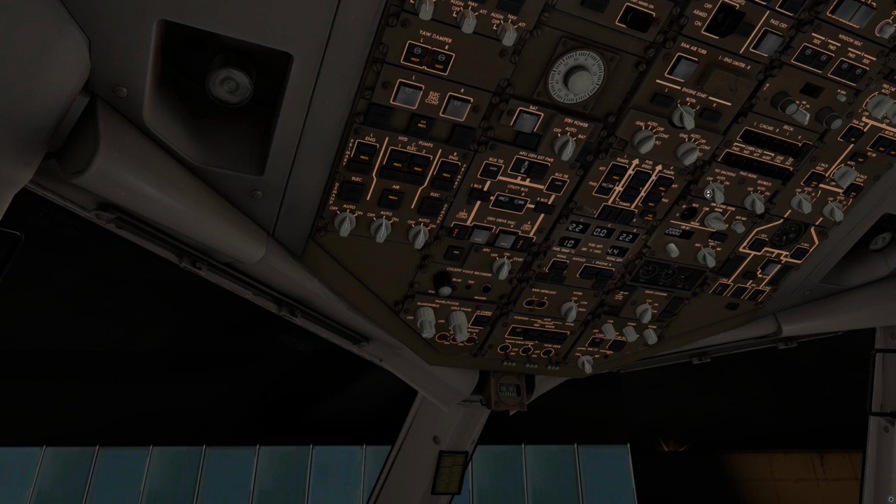I believe some airlines will leave the seatbelt sign off until fueling is complete. Once fueling is complete, then they'll turn the seatbelts on to notify any cabin crew that are guarding exits and doors that are being serviced by the ground crew. Then the flight attendants can resume their position once that light comes on and they know the refueling operations have been completed.